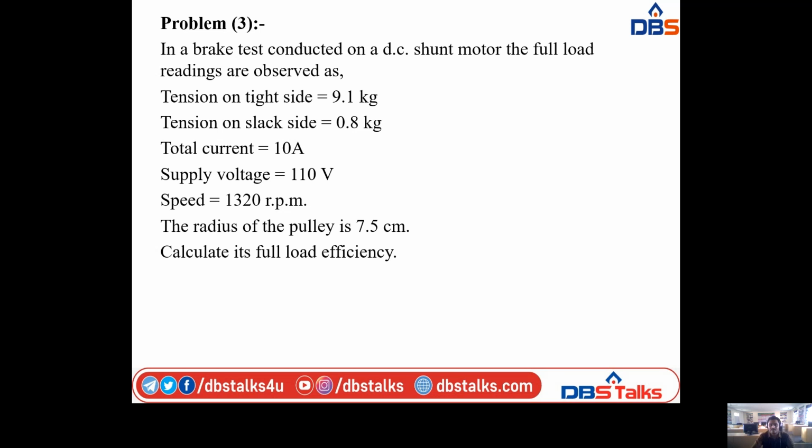And coming to the total losses, the total loss is a combination of armature copper loss and series field copper loss plus stray losses. So here the armature copper loss is 409.6 plus series field copper loss 600 plus stray loss 615.2, and finally we have the total losses 1624.8 watts. And output of the generator, they already gave, that is the input to the motor, 5220 watts, and input to the generator is equal to output plus losses. So here the input to the generator is 5220 plus 1624.8, that is the total losses. So we have the input to the generator 6844.8 watts.